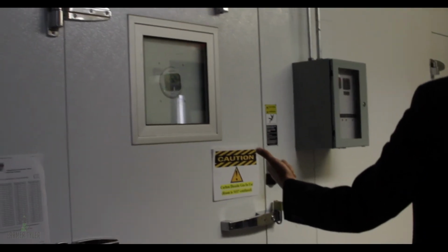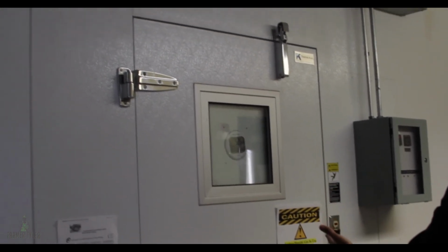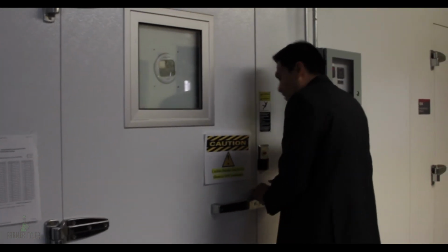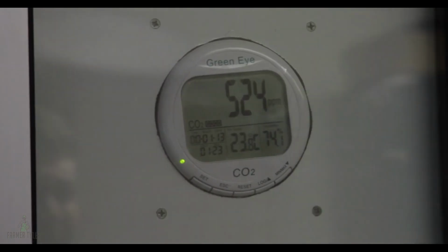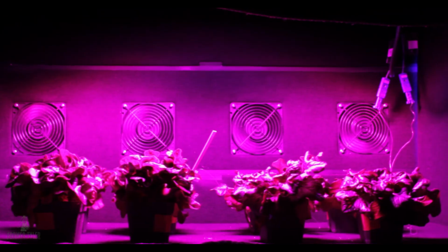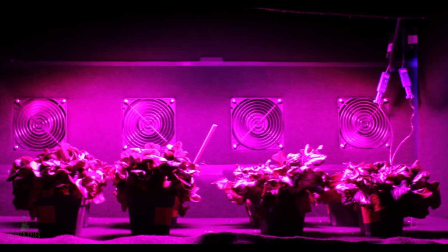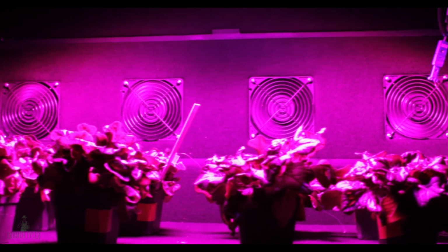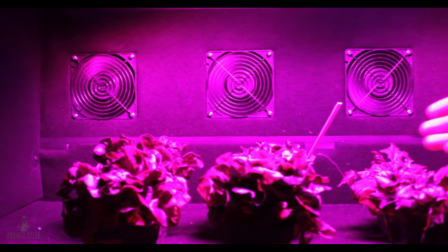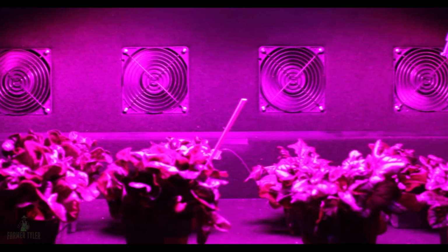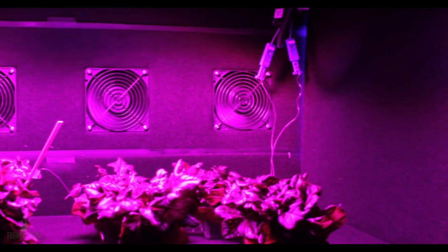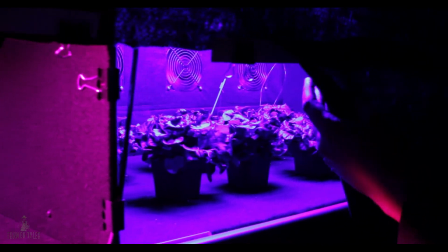We can put eight different light qualities, temperature, air velocity, and relative humidity. All out of a cooler? Yeah. So awesome. You can see back there where we have those fans. So we create a laminar airflow through here. So when you grow plants indoors, if you don't have laminar airflow, you're losing efficiency on your plant growth. We have thermocouples to measure the temperature in the leaves and temperature in the substrate. And then we have, of course, light quality treatments. Some of the different light quality here.